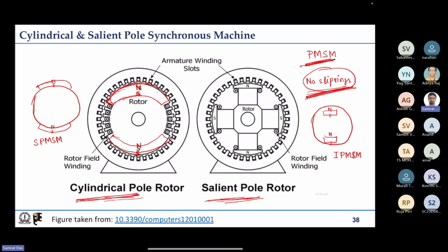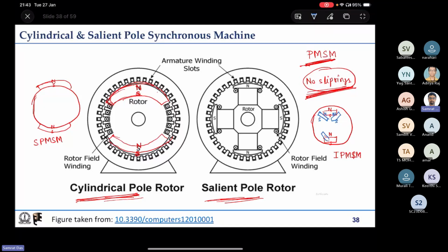And there are many ways to put the winding, put the magnets, all those things. I'm not going to discuss that as of now. It is doing the same thing, it is just producing magnetic fields. Now there are structures, so in what all directions can you put the magnetic field? Instead of a simple magnet like this, it is possible to put two magnets in V shape like this. Similarly, this side is north, north, south, south. So same thing, it is possible to put in V shape.